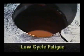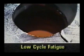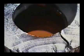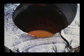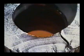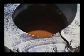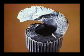Low-cycle fatigue occurs much faster than high-cycle fatigue, taking fewer cycles to reach final fracture. Since the crack propagates faster, the surface texture is rougher on low-cycle fatigue fractures. The color is a darker gray, reflecting less light, and the beach marks are more widely spaced and easier to see. This type of fracture is usually caused by severe cyclic overloading, and we should expect the final fracture size to increase. Notice the rough texture, prominent beach marks, ratchet marks, and a large final fracture. All these facts indicate low-cycle fatigue.